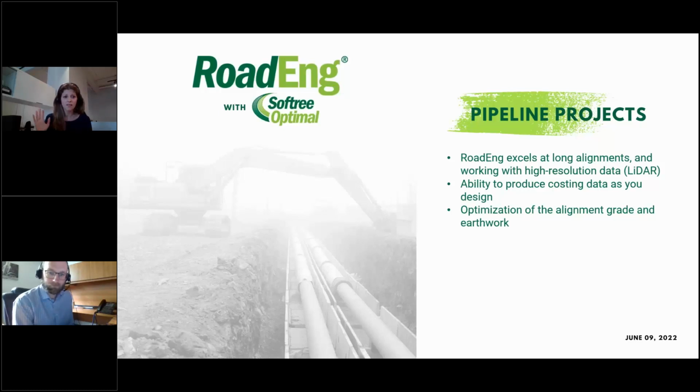The one shortcoming that we want to talk about, as well as the workaround for it: common practice on the road side of things, which is where we were founded, is that vertical curves are based on parabolic curves. Obviously in the pipeline industry, circular curves are the thing. So the workaround is a close approximation. We can use a multiple of 100. For a K value of 1, it's approximately equal to a radius of 100 meters. Something that I'm sure Matt will touch on a little bit more as we get going.